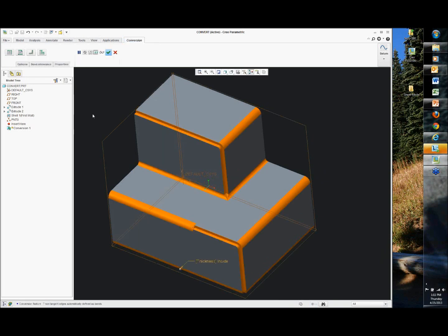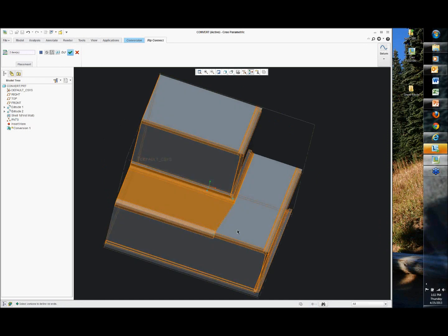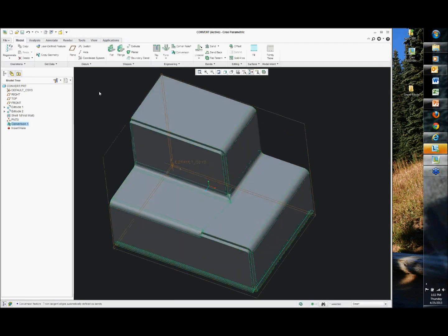So it's still not able to unfold, because we still have this problem inside here. So that's a rip connect. And I'm just going to grab the two, and you can see it rip. Now I purposely made this point offset from here just to show you that it's going to rip between those two, and it's going to stay pretty dynamic. So when I'm done with this, I can go back to the point and say, oh, you know what, it's not the way I want it. I really want minus 1.5. Get to the other side of that.